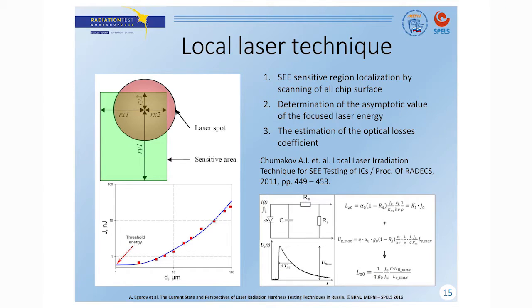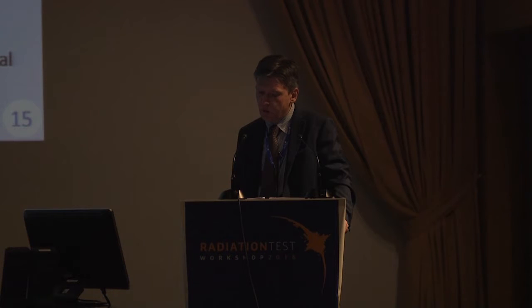So we also developed the so-called local laser irradiation technique, which allows us to estimate the SE threshold without performing heavy ion tests. This is a very special technique, and in Russia we use it as a last resort when it is impossible to irradiate the IC by ion beam.